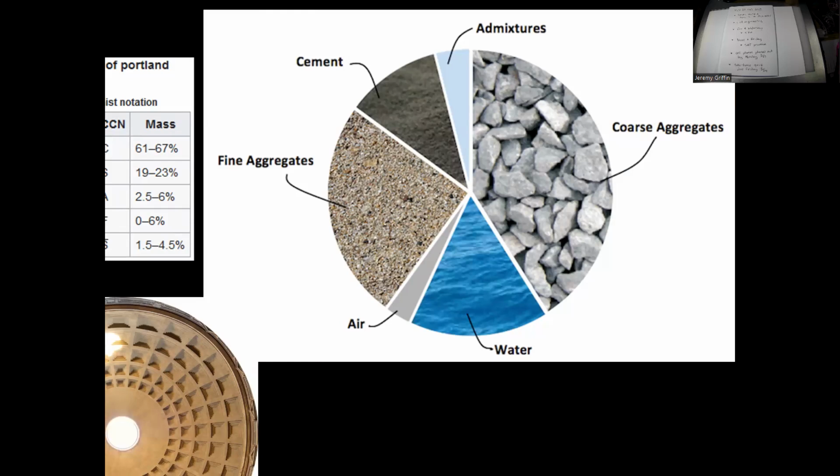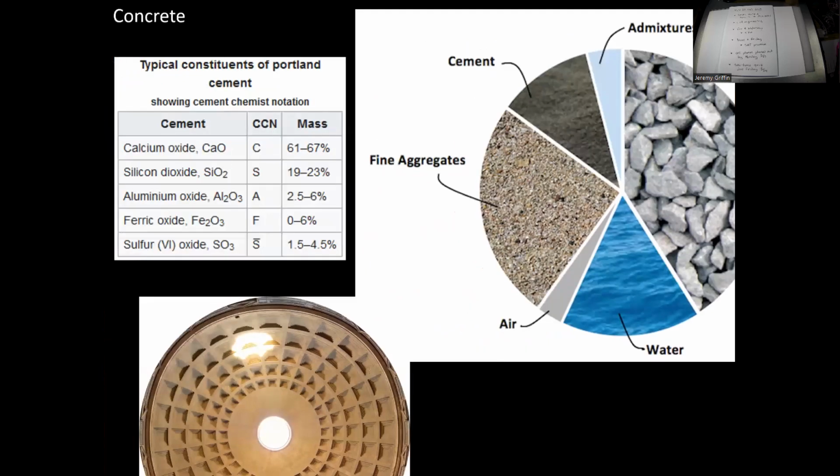What actually happens is that the concrete undergoes a chemical reaction with the cement, in our case, modern day cement, like a Portland cement, right? And that chemical reaction is exothermic, so it releases a bunch of heat energy. So the concrete actually cures, kind of like Elmer's glue, right? There's a chemical process, a chemical reaction, and it will harden. Also, this process releases a bunch of carbon dioxide. One of the big contributing factors to global warming is just concrete construction. Okay? Just this process here.